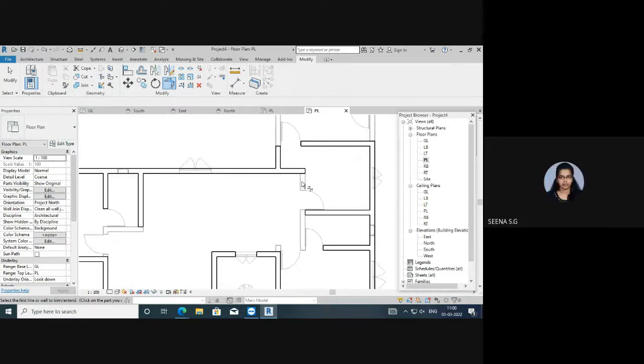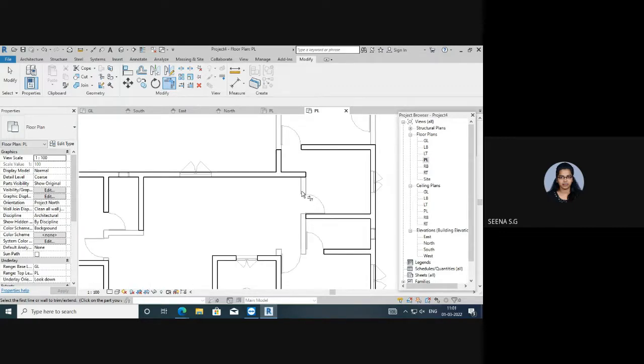Okay, actually this application is only applicable in the corner cases. So we can connect one horizontal and one vertical wall at a time. If we want to connect two walls, one wall must be in a horizontal direction and another one in a vertical direction. So we want to create a vertical wall. We have only the horizontal wall, but we didn't create any vertical wall in that direction. So here we want to create a new vertical wall, then we can connect.